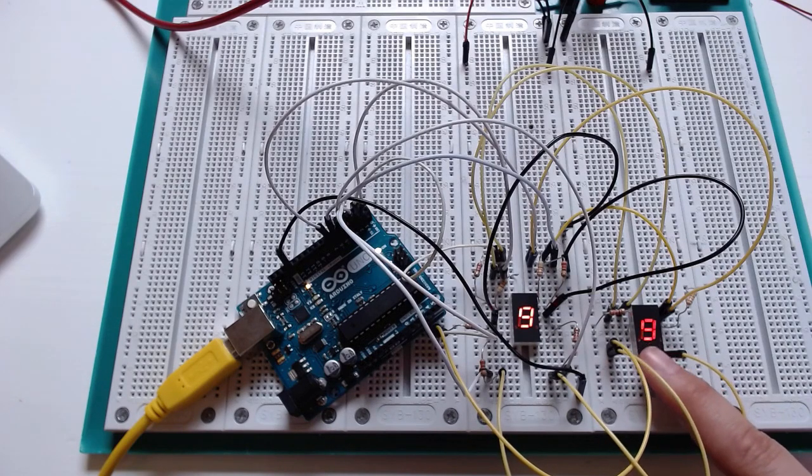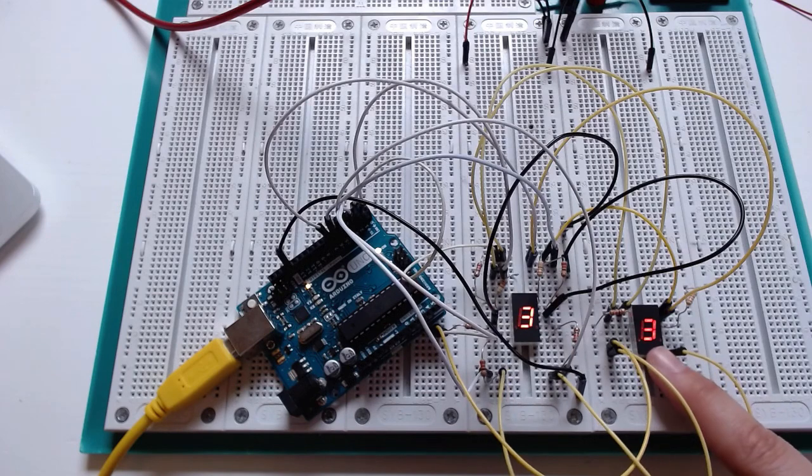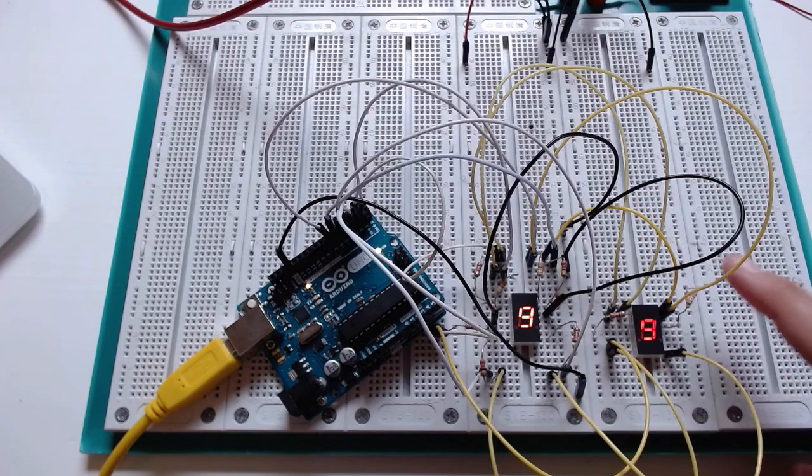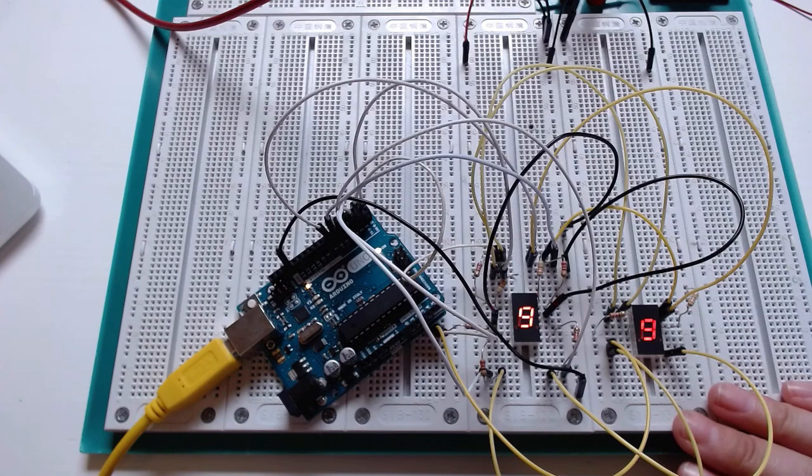In fact, you'll notice that it's brighter when there's numerals like 1 with only 2 LEDs lit up versus numbers like 8 and 9 where there are many LEDs lit up at once. So this is not the correct way to wire things. You might think that, oh, I only want to wire 2 things rather than 7 things, but it is too good to be true. The only way to properly wire up a segmented display is to have a resistor on every single segment.